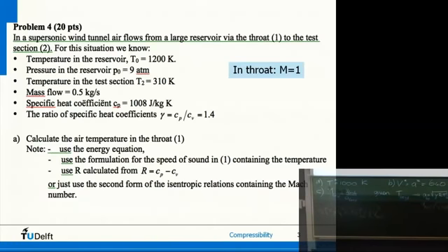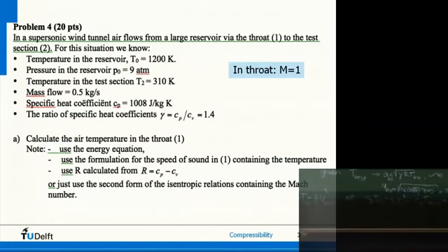Both is actually fine. We need the temperature and we need the speed. We have the temperature and the speed in the throat. Perfectly fine, it works. For the reservoir, we have the speed, almost 0, so we can assume 0, and the temperature, it will work as well. So both will work, only one is a bit less work, namely the reservoir, because we don't have to compute half V squared. As long as a streamline goes through it, because we integrated it along a streamline, and streamlines of course go from the reservoir through the throat to the test section. And I chose the reservoir.